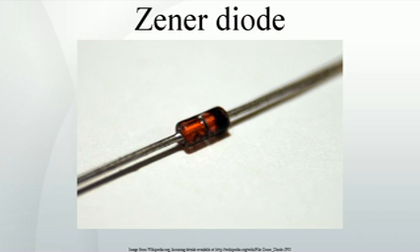Operation. A conventional solid-state diode allows significant current if it is reverse biased above its reverse breakdown voltage. When the reverse bias breakdown voltage is exceeded, a conventional diode is subject to high current due to avalanche breakdown. Unless this current is limited by circuitry, the diode may be permanently damaged due to overheating. A Zener diode exhibits almost the same properties, except the device is specially designed so as to have a reduced breakdown voltage, the so-called Zener voltage.